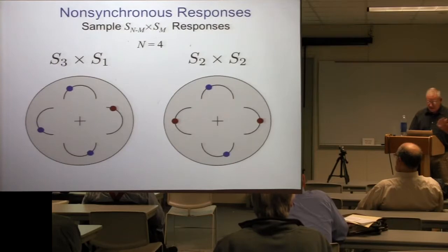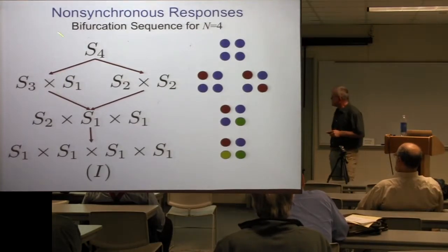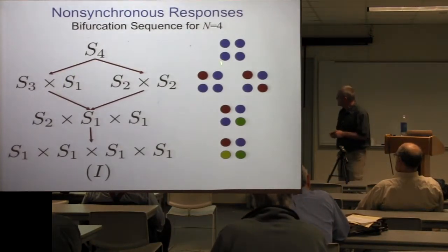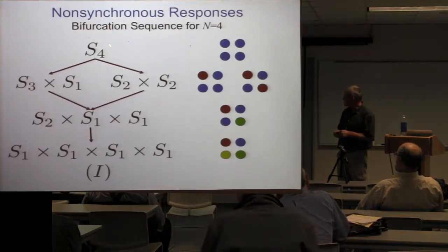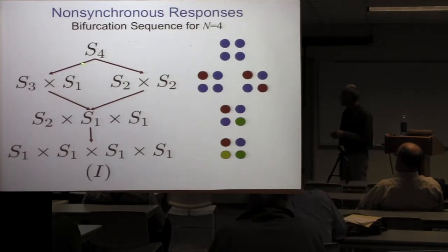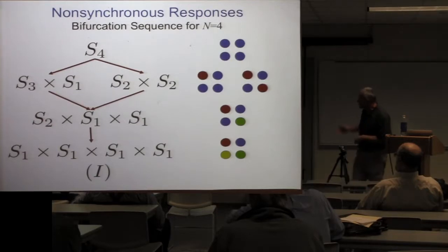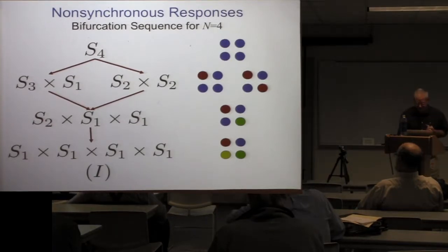And a big question is, are they stable? Is the bifurcation subcritical or supercritical? Our equations are so messy that we just do numerics. But basically, there's a bifurcation sequence that's expected. This represents the symmetry for complete interchange of 4 absorbers. The first instability will yield these 2 kinds of solutions, and then the next instability will both have this type of symmetry where 2 absorbers are identical, and then you have 2 others that are doing something different, and then of course you'll go to a place where you have all 4 absorbers doing different things. So this is what indeed you see.